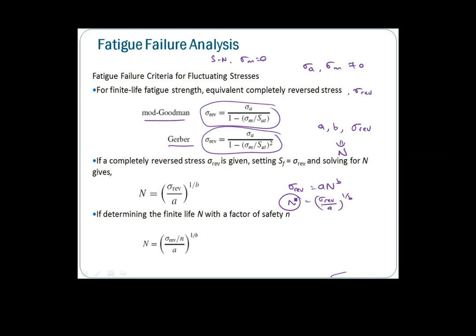All right, so that is how you predict. Only when it is needed. When you are below the endurance limit, then you have infinite life, and you do not actually need to predict. We know that it's infinite life, right? But if your N is lesser than 1, then you have a finite life, so you have to predict your life.